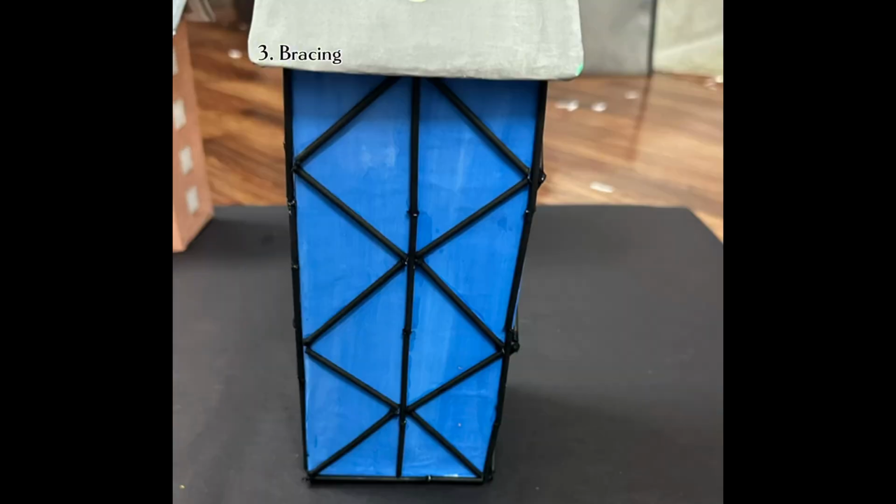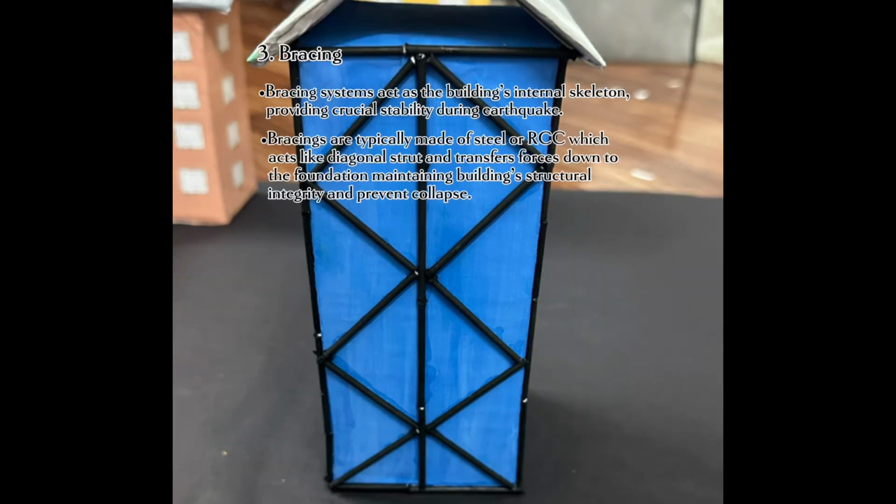3. Bracing. Bracing systems act as the building's internal skeleton, providing crucial stability during earthquake. Bracings are typically made of steel or RC, which act like diagonal struts and transfer forces down to the foundation, maintaining the building's structural integrity and preventing collapse. The specific type and placement of bracing depends on the building's size, shape, and expected seismic loads.